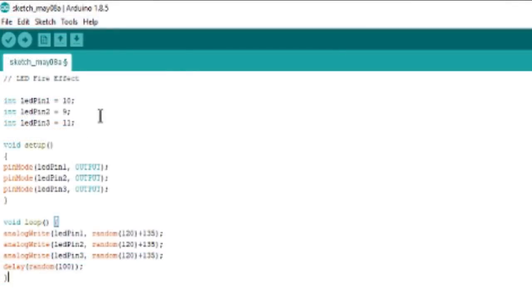Now, what you need to realize about this software is that these first 3 lines right here initialize the 3 pins that your 3 LEDs are connected to on the positive side of the circuit, pins 9, 10, and 11. These 3 lines here set them up as output pins, so that the electricity is going to be flowing out through them to our LEDs. And then these lines down here actually set up the flicker of the LEDs that makes the fire simulation. What you're going to see here is that these first 3 lines set a random brightness. The brightness is set by this data right here, which in each case is a random number less than 120